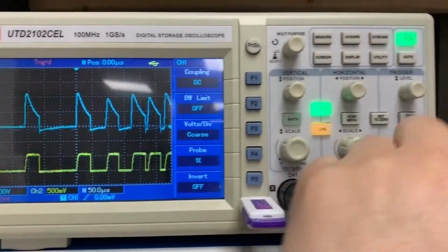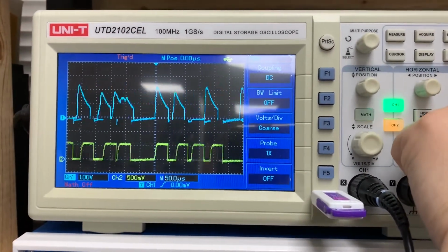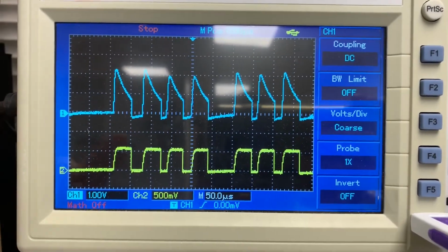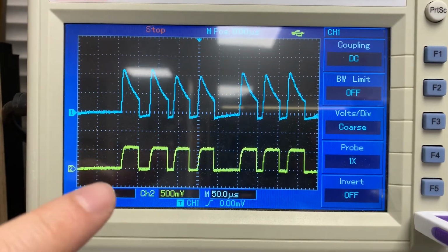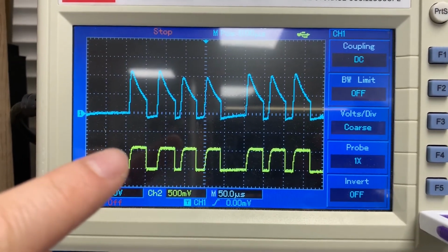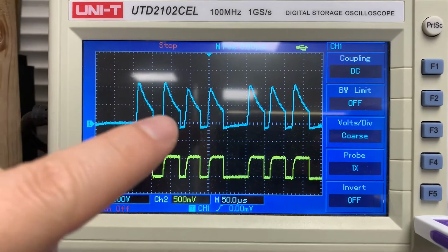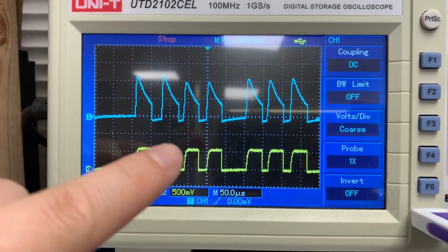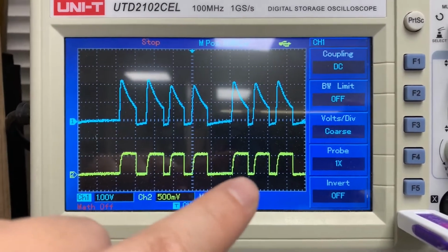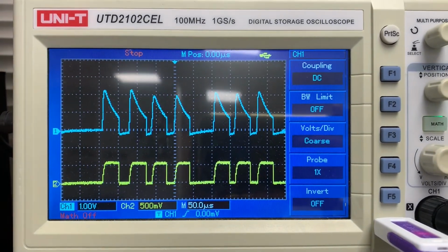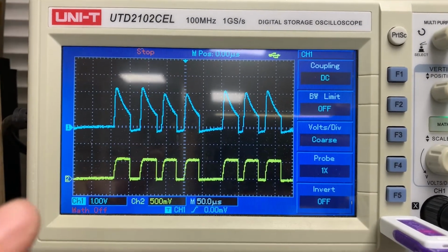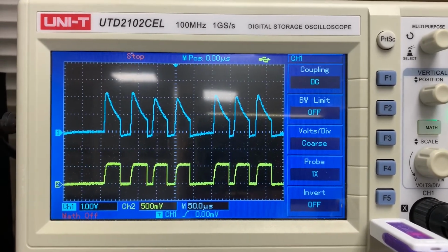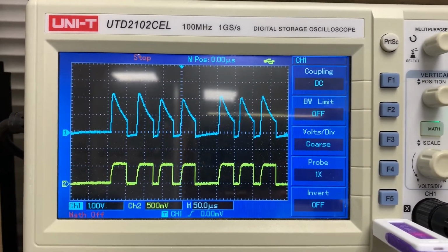So if I do this, let me just pause this here. You can see some nice waveform that we can read in from Arduino, going from 0 volt to 5 volt. And basically what we did is we turned this into a digital signal that we can count using any microcontroller. So what's next is going to be programming the Arduino so that we can actually read this and count the number of photons that we detect within a certain time period.